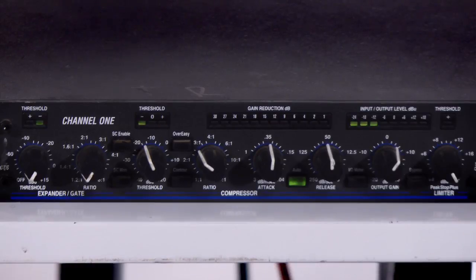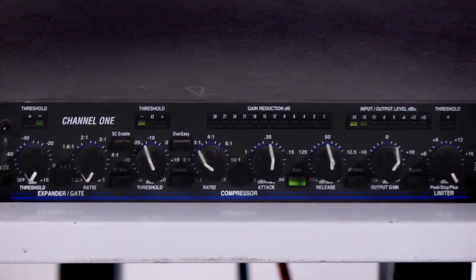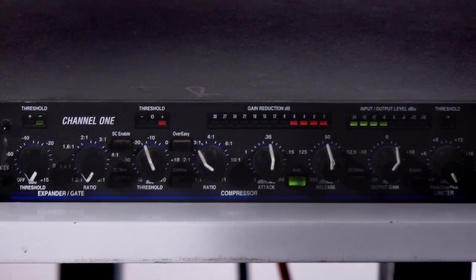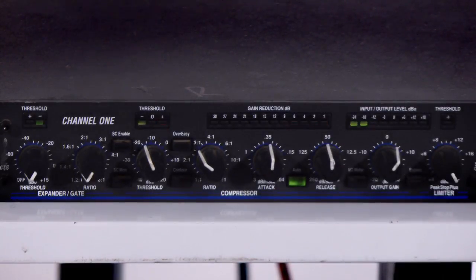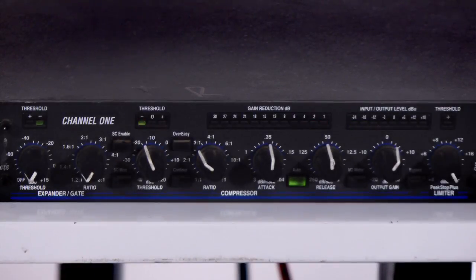If I talk quietly, you will notice there is no gain reduction. We have now moved our own effort below the threshold. If I talk with medium excitement, we will get some gain reduction. But if I go fully excited and I really start to increase my dynamic range, then the compressor will work harder and harder to compress. And you should be able to hear this as a squashing of the signal. Let me help you to hear this difference.